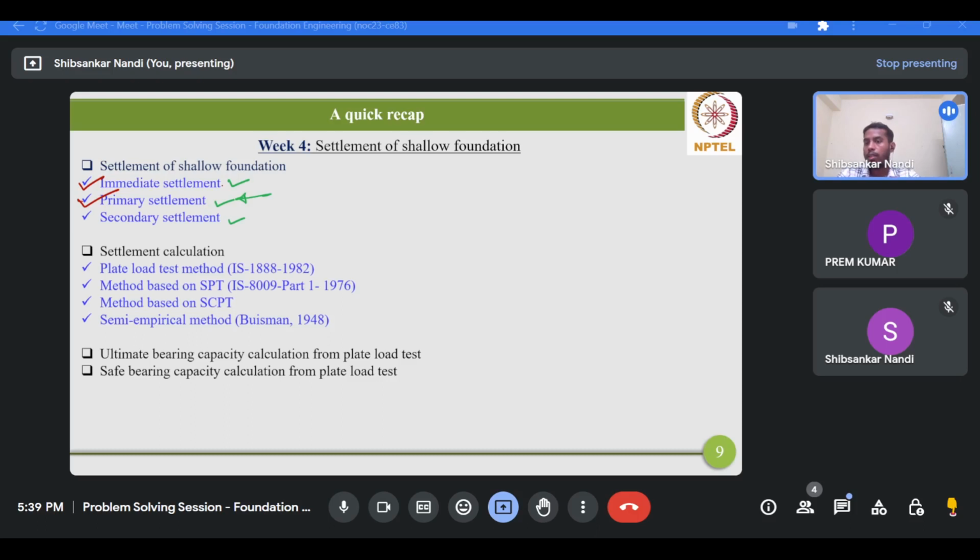However, for cohesionless soil, it's very difficult, and we have discussed this in the earlier sessions as well, to extract an undisturbed soil sample for determining the settlement through laboratory investigation. It becomes very difficult because the structure of the soil mass gets very disturbed during the sampling procedure.